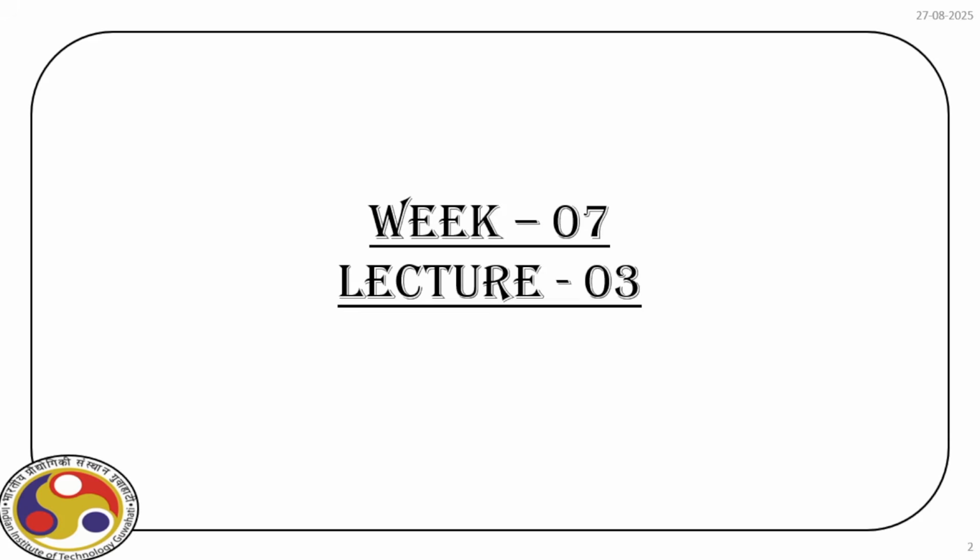Hello everyone, let us continue our discussion. We are in week 7 and this is our third lecture. If you recall, we already derived the bending stress distribution over a section and we derived this expression: sigma by y is equal to M by I is equal to E by R, right?